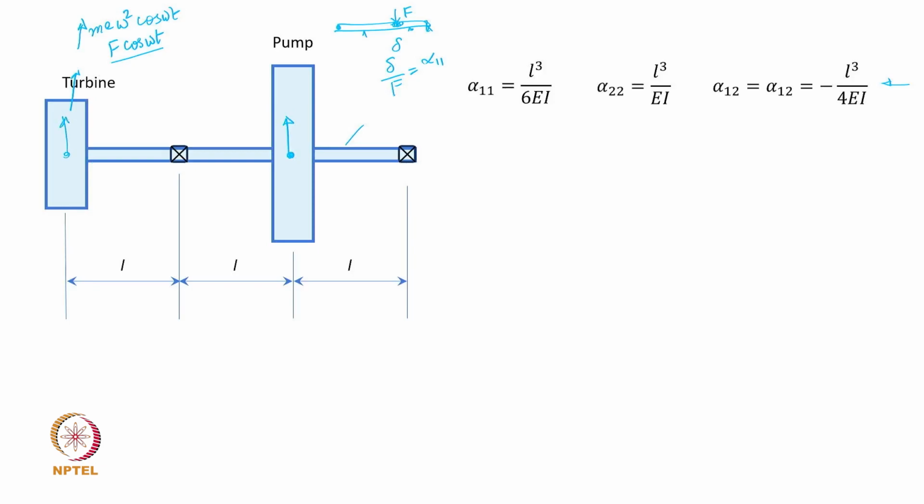Those things aside, if we simplify the problem here to understand how the response to any unbalance or any harmonic excitation of such a lateral vibration system is obtained, what we now say is that y1 is not going to be only given by this, but we include the contribution from the unbalanced force. This unbalanced force appears just like these inertia forces.